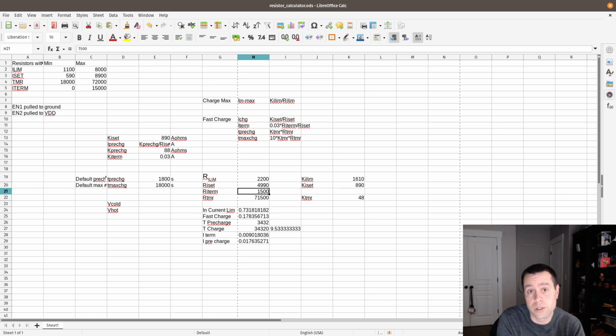It's requesting a certain limit from the host, which in this case is my computer, a laptop or a tower or whatever it may be. If you have 5 ports and each of them wants to request 500 milliamps, now you're at 2.5 amps, and the one hub connection just can't do it. You can only source so much. There are current limits in everything, in your host and your laptop and in the hub and things like that.